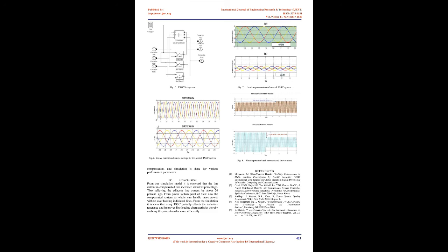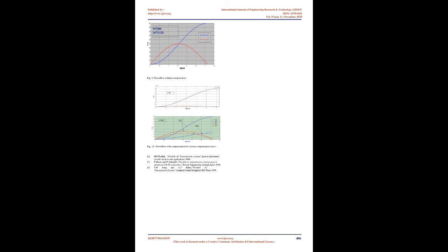An example of an application based on this concept is presented in the literature. This compensation system has the advantage of being very simple. However, it does not allow continuous control. If the connection and disconnection of the capacitors is made at sporadic switching, no harmonic problem occurs. Depending on the frequency at which the thyristors are switched, harmonics or subharmonics may appear. In this arrangement, it is interesting to choose the value of the capacitors in such a way that many different combinations can be achieved.